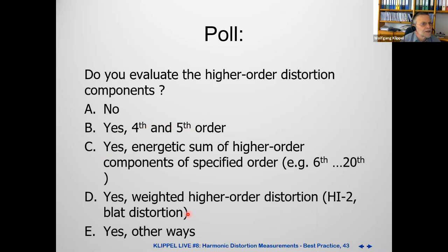Here I see the result. The majority say no. Why? Because everything becomes now a little bit more complicated. And it is really complicated. And the main enemy, again, is noise. The higher order harmonics are usually very noisy. If you are working with them, you have to really do a near field measurement like here, to put the microphone very close to the speaker.